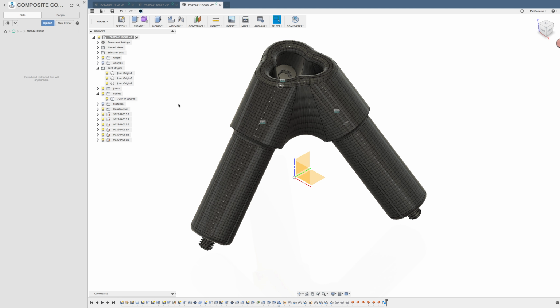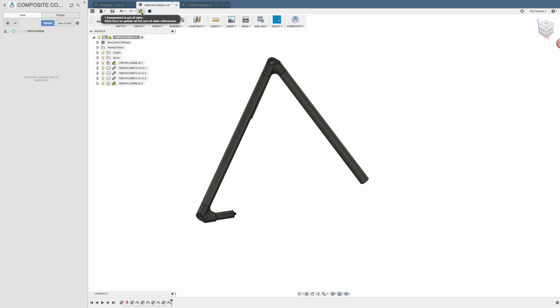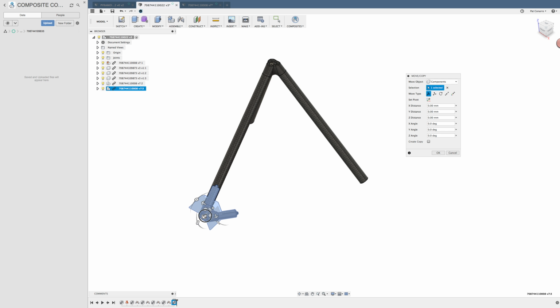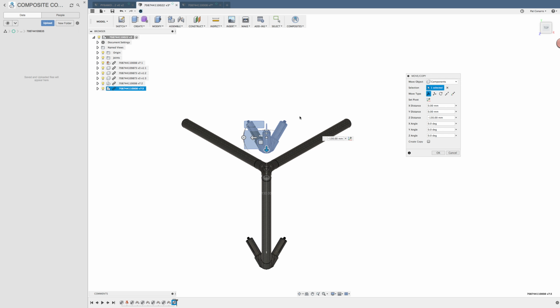Okay, so let's just work on the cost, but I want to go in and talk a little bit further about the master assembly. So here's the master assembly, which I'm making the pyramid. I've already brought in some tubing, so I use this standard tubing that we've got right here, and this all comes in here. So what I want to do is copy this. So I click on it and I go Control C, Control V, and I look at my top view. I'm going to spin it around.